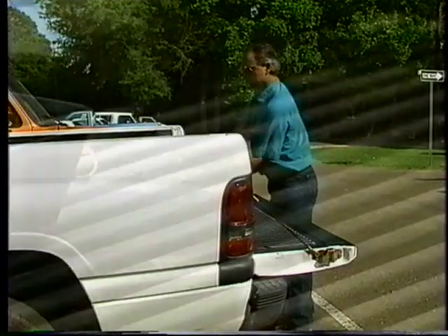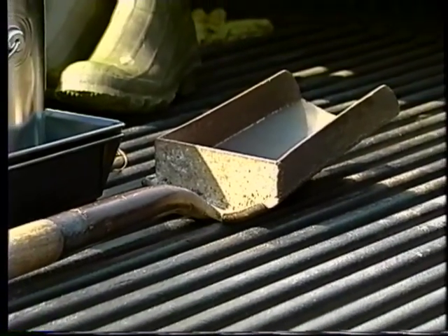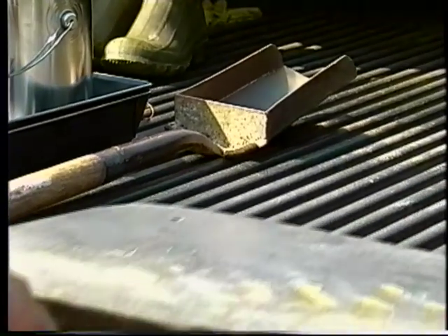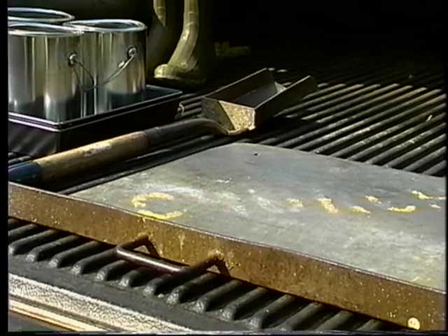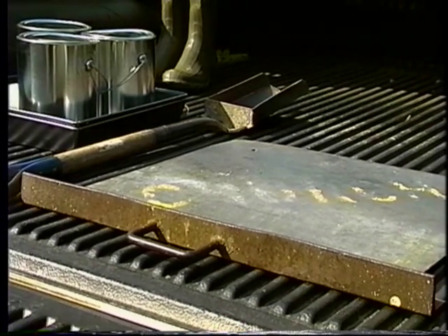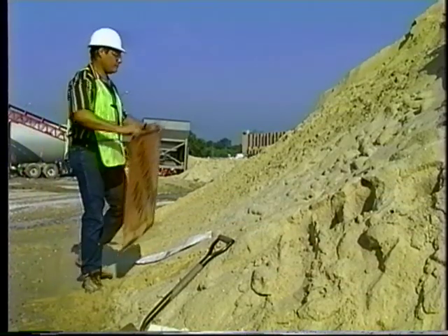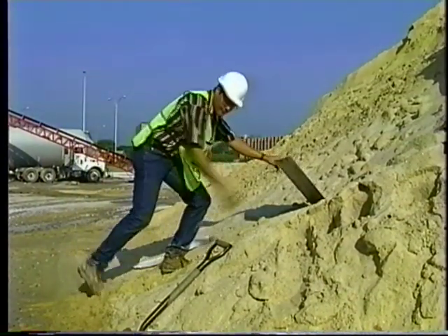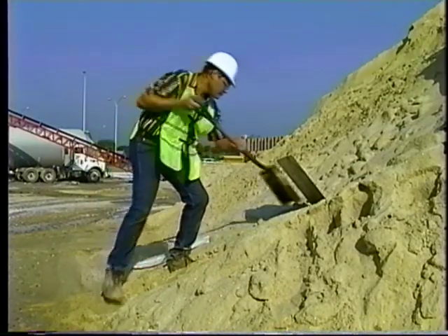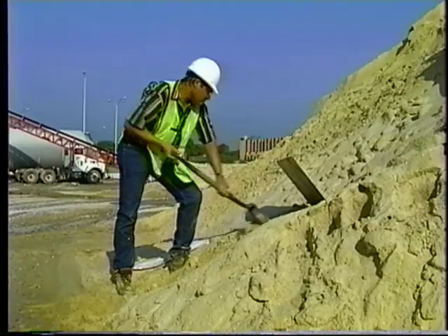The sampling shovel has upturned sides that prevent the possible loss of material. The shield is used to prevent the movement of unwanted material into the sampling area. It must be strong enough to perform this function without bending or giving way under force. A metal sign can be used as a shield when sampling soils or fine aggregates such as sand. A specially designed shield may be necessary when sampling heavy aggregates such as crushed stones.